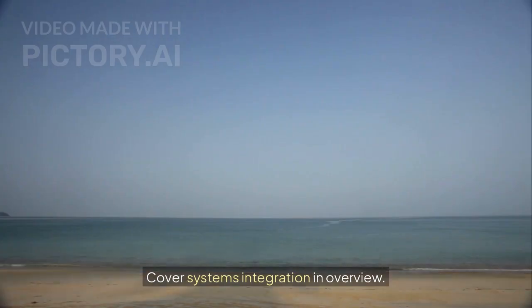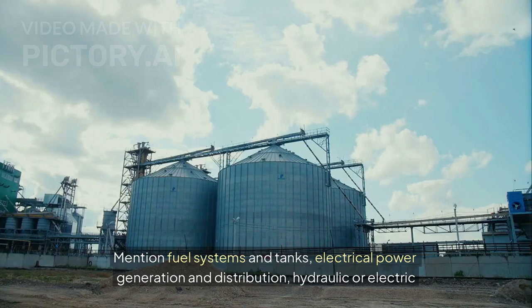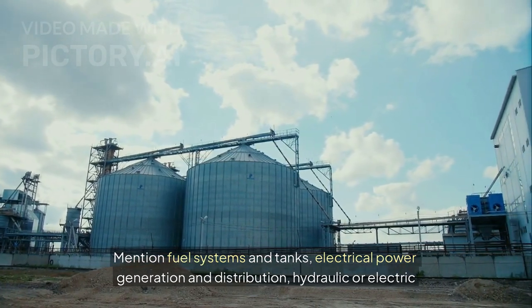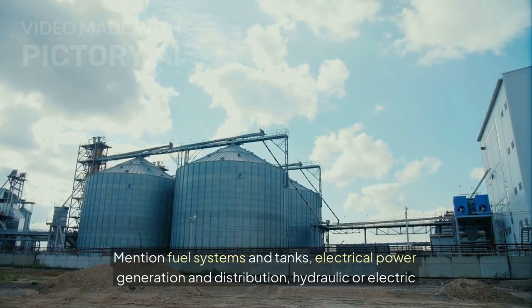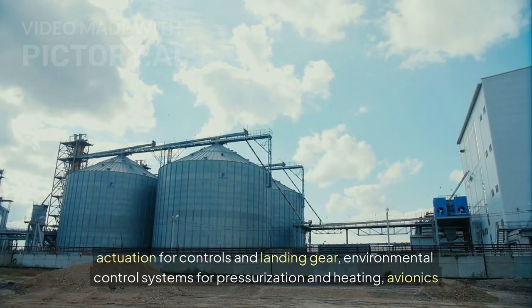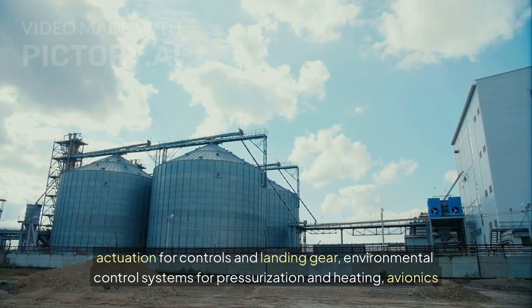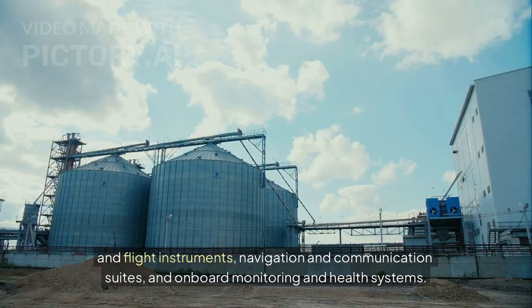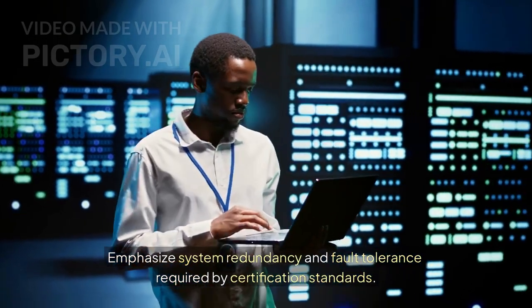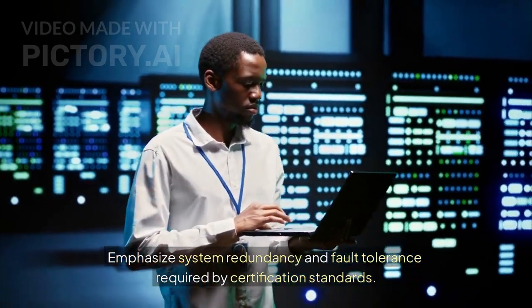Cover systems integration and overview. Mention fuel systems and tanks, electrical power generation and distribution, hydraulic or electric actuation for controls and landing gear, environmental control systems for pressurization and heating, avionics and flight instruments, navigation and communication suites, and onboard monitoring and health systems. Emphasize system redundancy and fault tolerance required by certification standards.